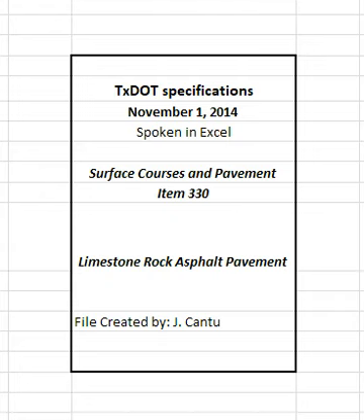4.6 Irregularities. Immediately take corrective actions if surface irregularities, including segregation, rutting, raveling, flushing, fat spots, mat slippage, color, texture, roller marks, tears, gouges, streaks, or uncoated aggregate particles are detected.